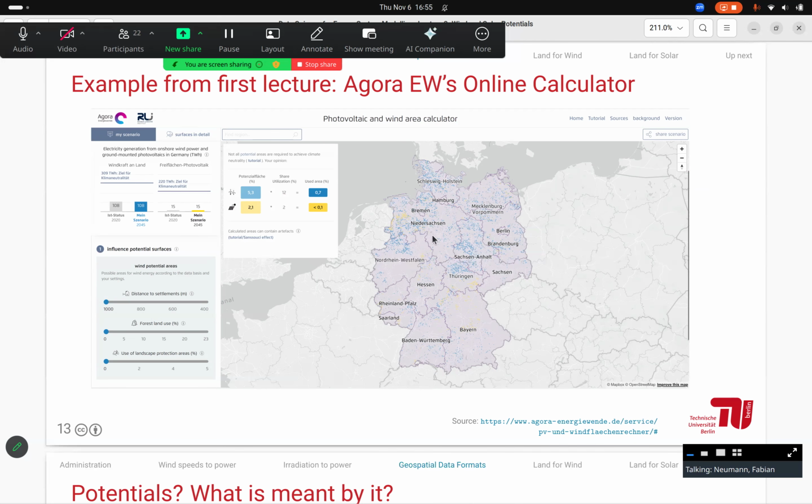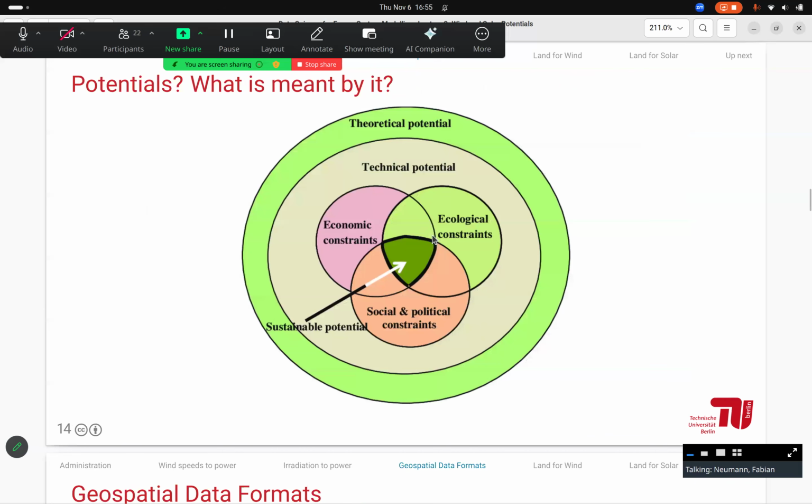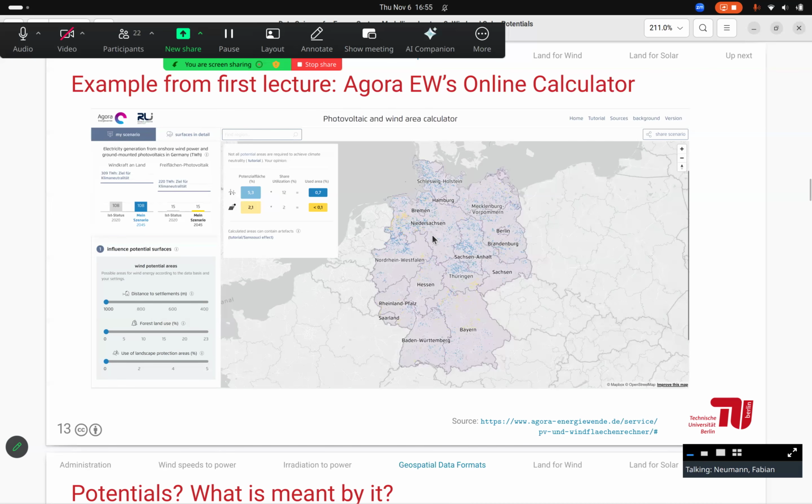it seems to be the case that at least none of the obvious reasons like natural protection areas, distance to buildings, type of land use, forests, and so on, speak against building a wind farm. It doesn't automatically mean that you should build a wind turbine there. There always also have to be the right wind conditions. You could have eligible area which has the worst wind speeds. Then, of course, it wouldn't be, from an economical perspective, eligible for wind turbine development. So that's land eligibility analysis, made for calculating potentials.